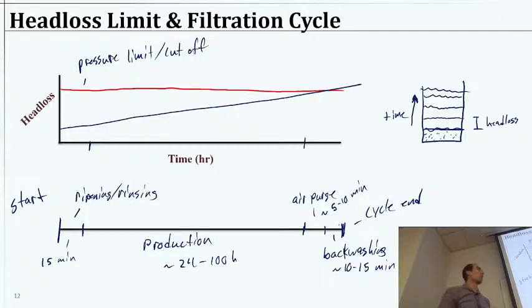So that's a really good question there, because it's an important concept. This is how we operate the filters, and at some point, if we designed it poorly and we put too much pressure, eventually it's just going to push apart the sand and say, I'm just going to go through. The sand itself will be too unstable structurally, will part, and you'll get all your water flushing through with no treatment. Probably the opposite of treatment now that it's had already collected some particles. Okay, does that make sense?